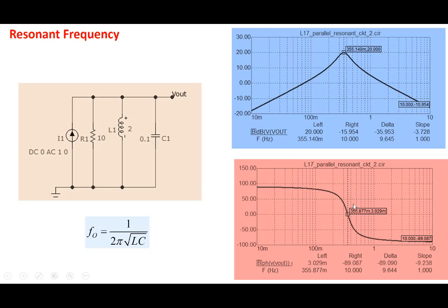So at the frequency at which phase is zero, which means power factor is unity, the voltage that developed here and the current are in phase with each other. So cos of phi is equal to 1, unity power factor here. So at the frequency at which power factor is 1, at the same frequency, the current reaches its maximum value here. So there is no ambiguity in saying what is the resonant frequency.